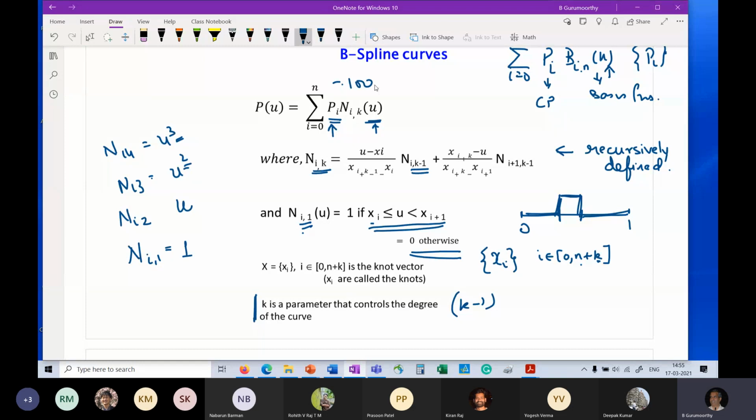And that's a very powerful thing, because you have so many more control points to move around and change the shape, add features and details to the curve without having to worry that the curve will not remain quadratic. It will always remain quadratic. So just by the choice of the way the basis function is defined, you have addressed the first problem: the flexibility in the number of control points is no longer linked to the degree of the curve.